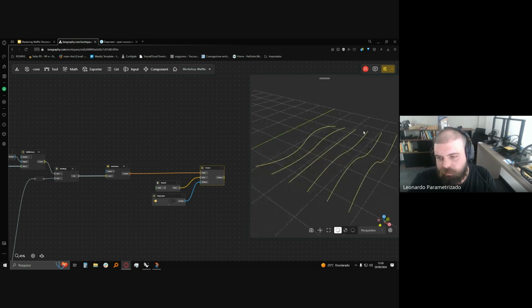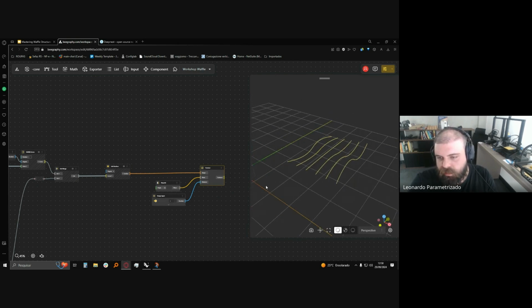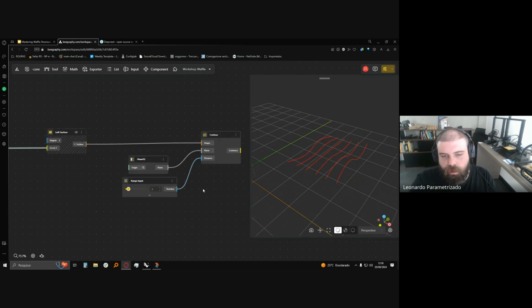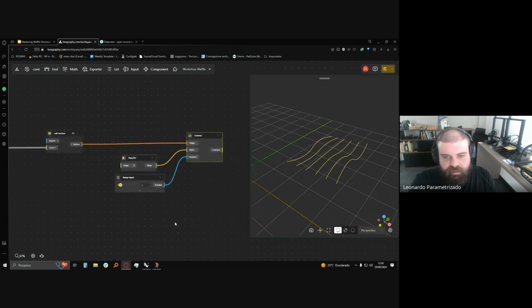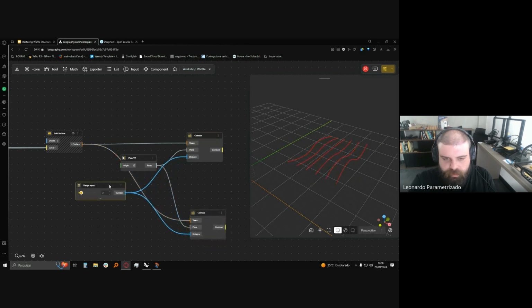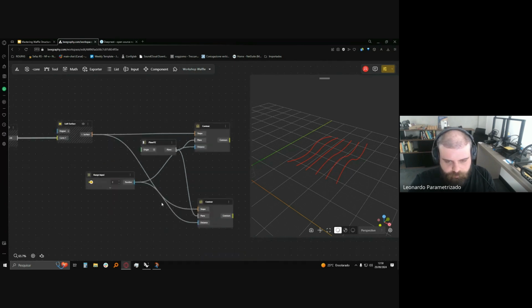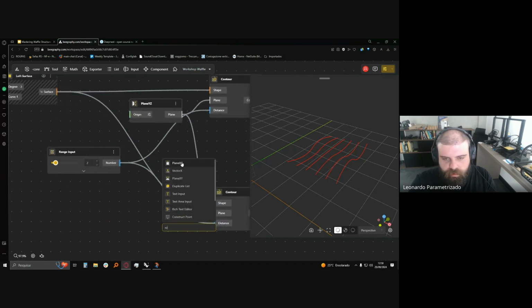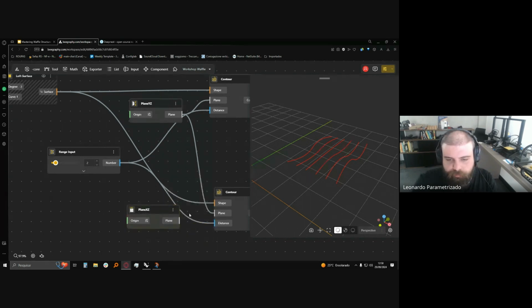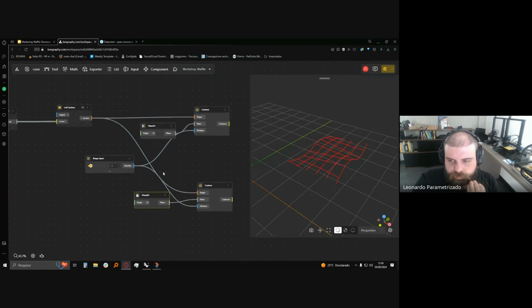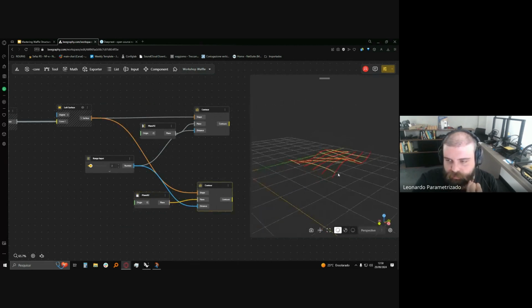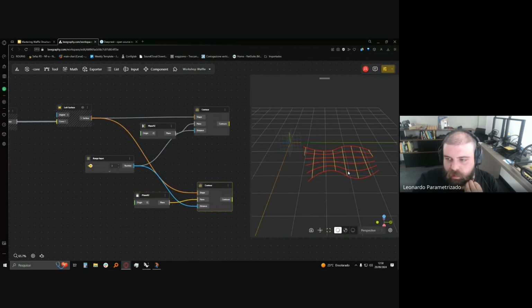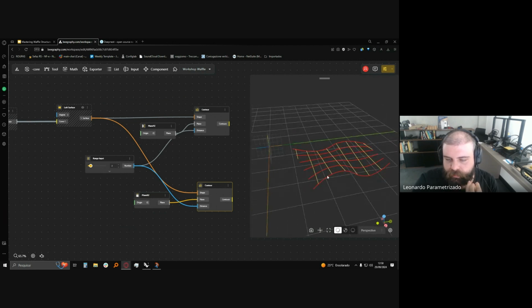So this is one direction, the X direction. I need the ones in the other direction, the Y direction. We'll be doing the same thing here. I'll be copying this node. The only difference is that I'll be changing the plane. This one is YZ; I now want the XZ plane. If I plug this plane here, then I have my contours in the other direction.